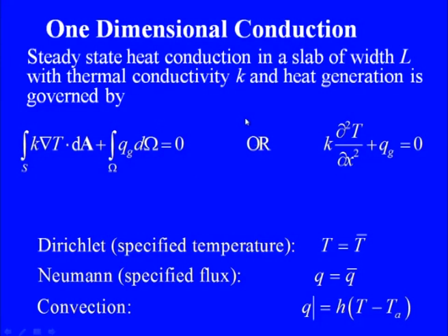As far as the basic discretization technique is concerned, it would be exactly the same even for a time dependent problem. The only difference would be that, in the case of time dependent problems, our discrete finite volume system would be a system of ODEs in time, which we can solve using the time marching schemes which we had discussed in the previous module.